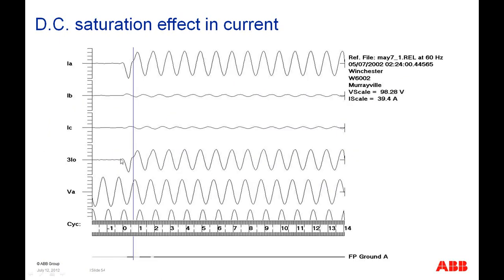Here's a picture of CT saturation. You can see this little blip here is where the CT had saturated for a little bit on the phase A current.